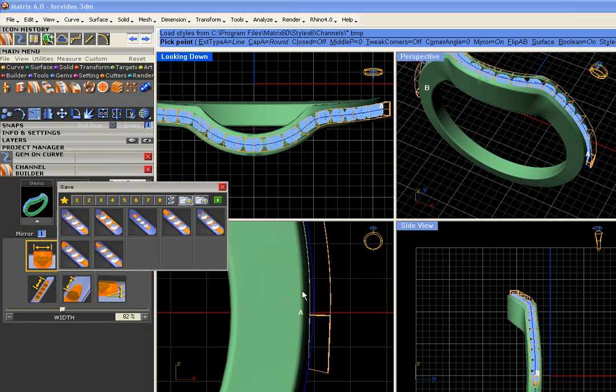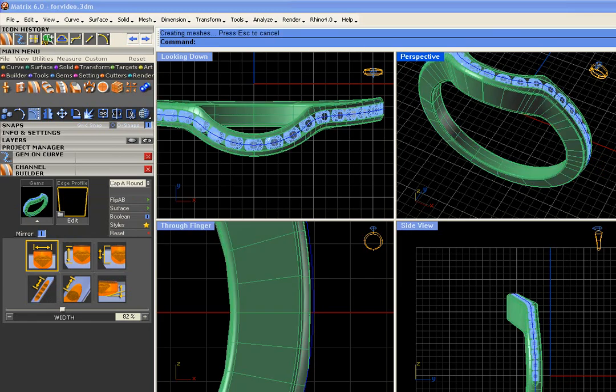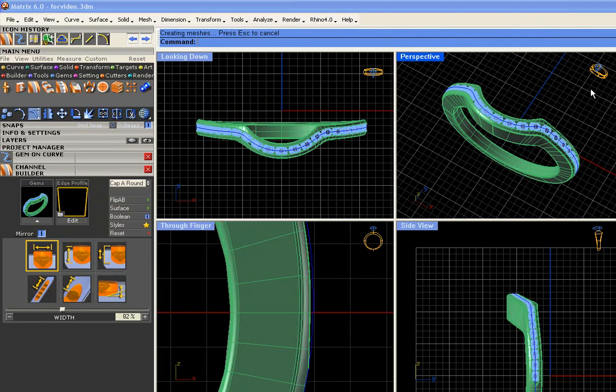That way, if you choose to make any changes to the ring, you can reapply the same style. And if you reapply it within this builder, you'll be able to get the handles back and continue editing it. So suppose you wanted a different taper for the top of the ring. We'll show you how to adjust all that with history. And then come back in, apply the same style, and then if it doesn't work, you can change other things about it with the handles. Okay. So when you've saved it, just close out this interface and press enter to keep your changes. And there's the channel cut.